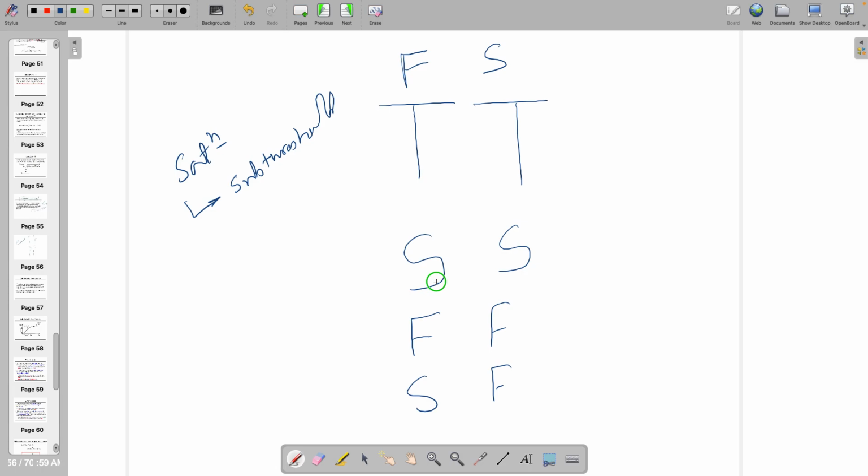Right? And similarly, if you are using it as a switch, you are expecting it to be in cutoff, but now if it is in subthreshold, it might happen that it can give you the required connection between input and output, and it can give you the wrong result, right? So those are the things. That's why subthreshold is very important. This happens mainly in circuits like biomedical, where you are keeping a very big size of W/L. So you have to design it in such a way that it works at PVT.